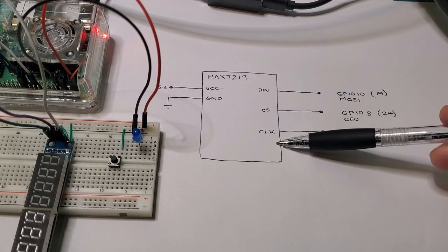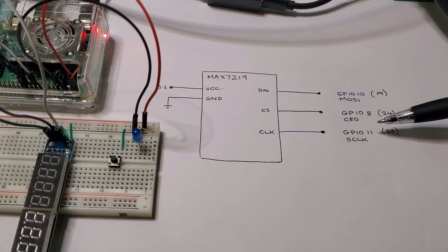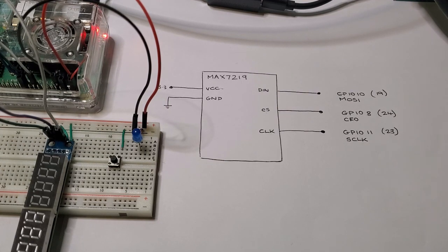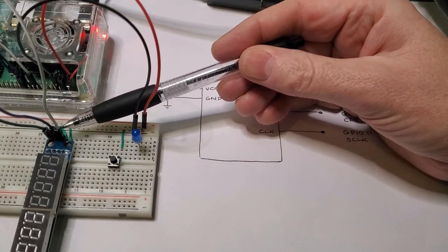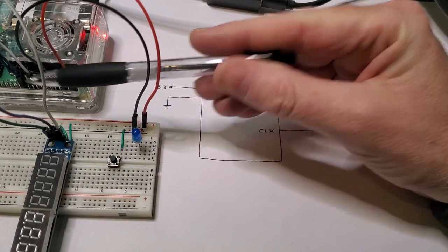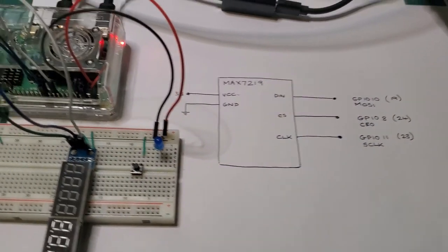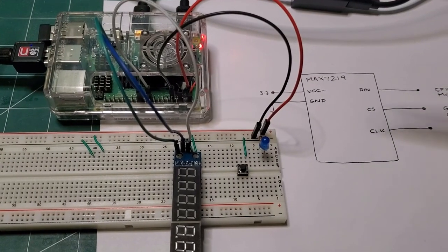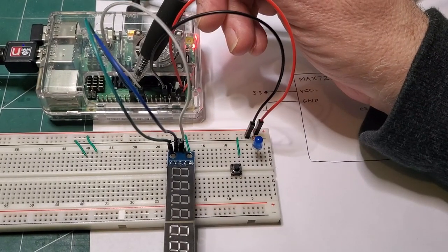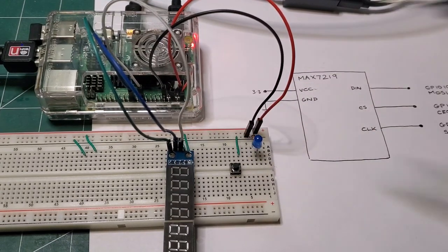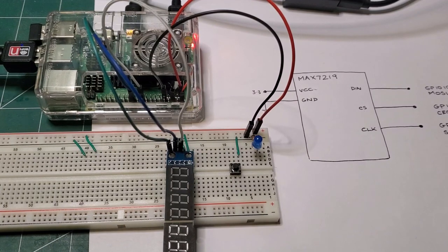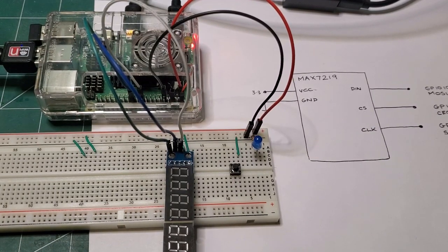And then finally, there's the clock, which comes from GPIO 11, header pin 23, and that's also referred to as SCLK. And as you can see over to the left here, we've got those connections coming in from the appropriate pins on the RPi. You actually can't see that. Let me move over a little bit. So here's that cluster of SPI pins, and then here's VCC and ground. So let's dive into the code right now. We'll see how to drive SPI.